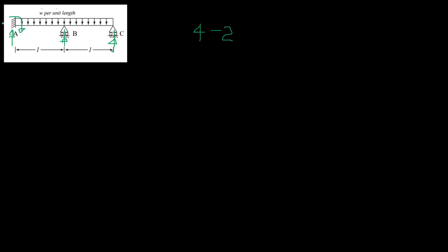Because you remove the horizontal force from the system, you can't use the horizontal equilibrium equation as well. So your three equations now become two. If you take the horizontal reaction, you have five unknowns, and you have the horizontal equation as well. So in any case, your statical indeterminacy is the same, right? It is 2. So that means there are two redundants. Due to that, you can't solve this system.